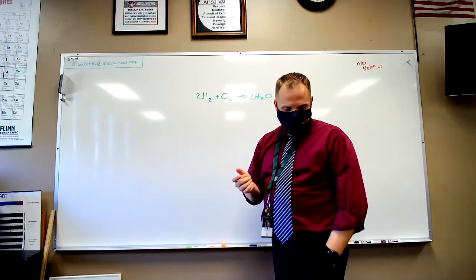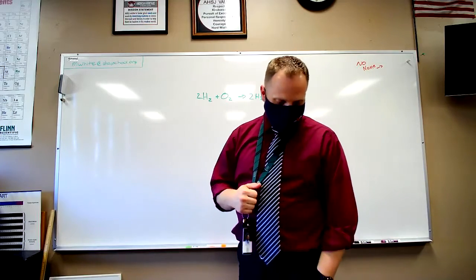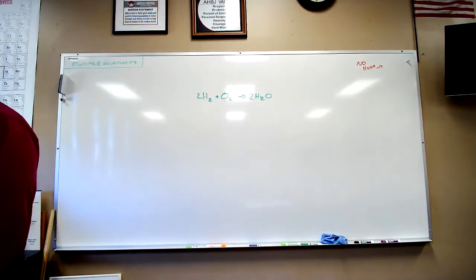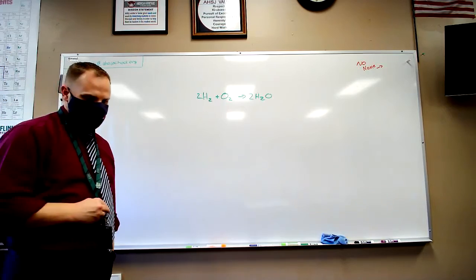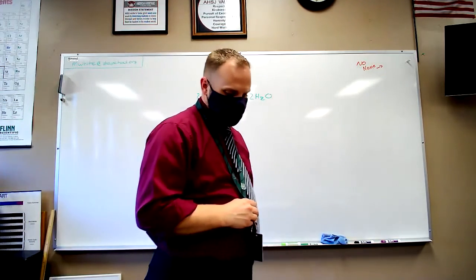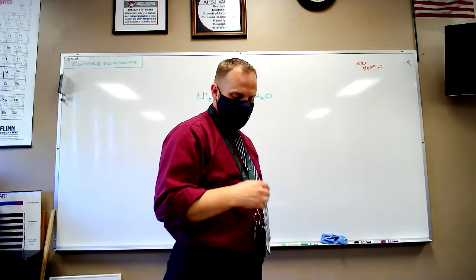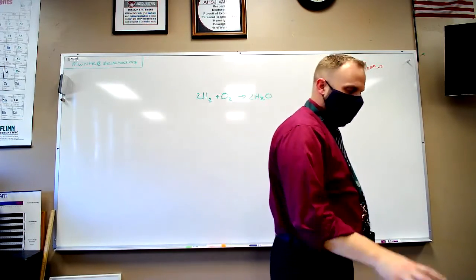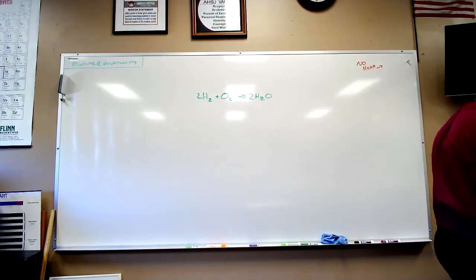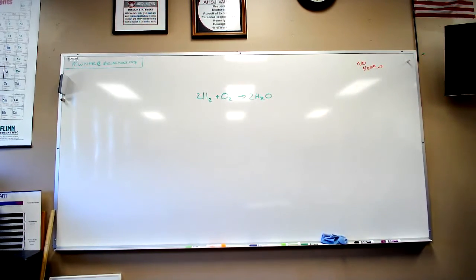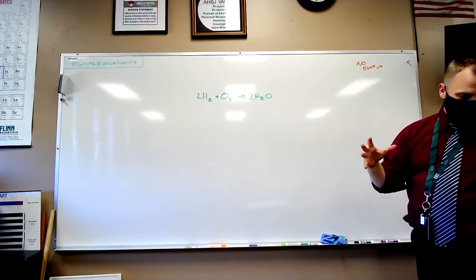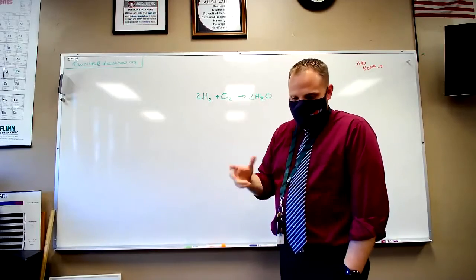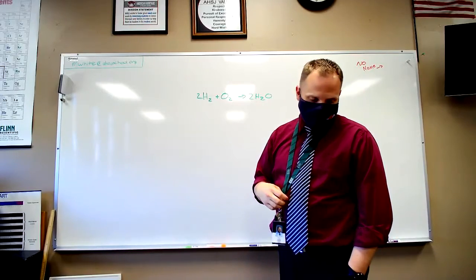If, however, the zinc gets damaged, the zinc will then start to act as the sacrificial anode. And so it will oxidize before the iron object that it's protecting. So galvanization protects in two different ways. First, it's a physical barrier. And second, it is a chemical sacrificial anode.